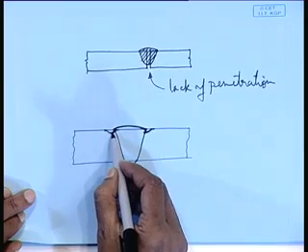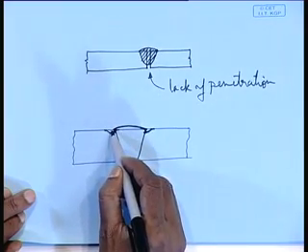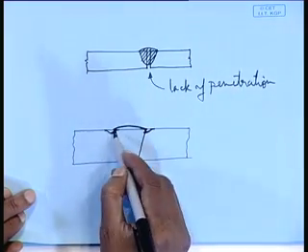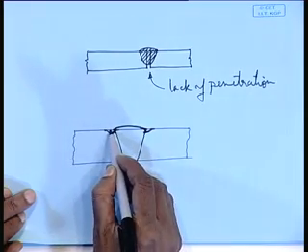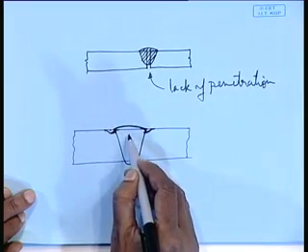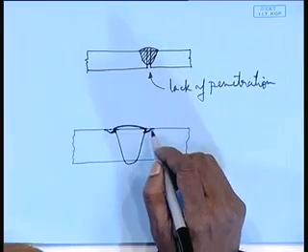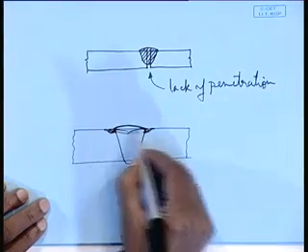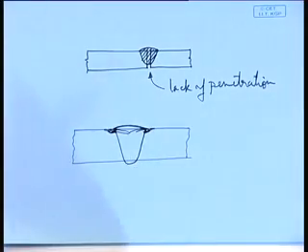Why? Because essentially the metal gets melted. If the speed is fast, the metal gets melted, and because of the high speed, the metal gets solidified faster before it could flow back and fill up the entire place. So, a kind of crater is formed, a longitudinal crater all along the length of the weld. It is speed dependent, meaning if speed is high, it generally leads to undercut.